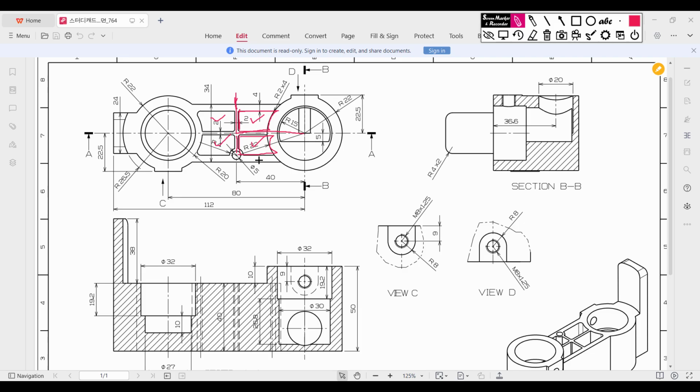Then I will extrude cut it. We can see it has an extrude cut of 40 unit. You can see this hidden line. That means they are extrude cut up to this 40 unit distance. So let's go back.